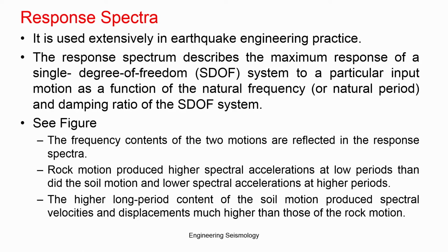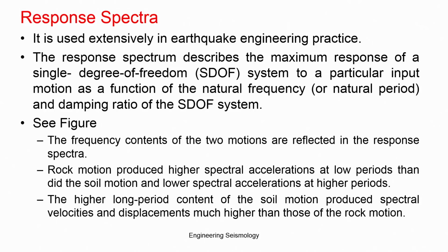The response spectrum, the spectrum, is basically a plot of frequency versus amplitude. The frequency can also be plotted as the natural frequency or natural period by taking the inverse. So it is the response of something plotted as a spectrum that is called a response spectrum. It is used extensively in earthquake engineering practice.